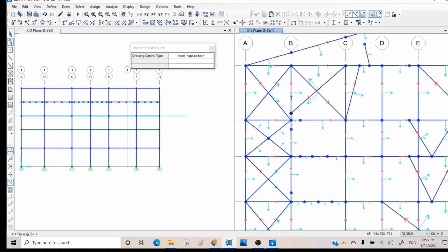Now, for example, if you want to come to the mid here, you need to come here and activate mid, and then you can connect it to the mid length of this beam. So I just put it back here. So this is for deform shape. So mainly those are what I wanted to discuss about frame edit.